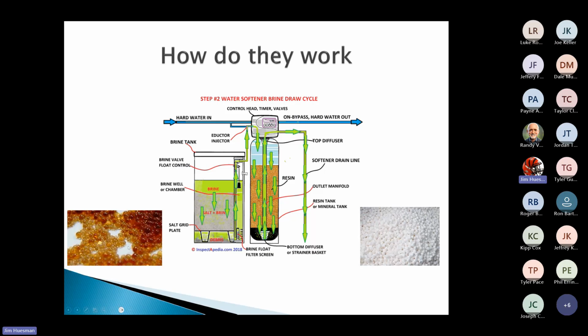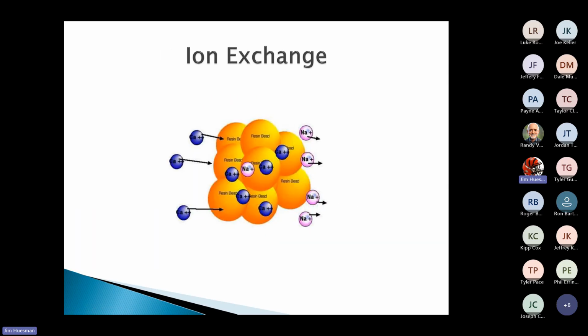But let's talk about what's going on with the media inside this tank. What is this media actually doing? How is it grabbing a hold of it? And the word is called ion exchange. All right, it seems very, very smart, but we're just exchanging one ion for the next. So when the media is set in the tank and it's new or after a regeneration, we have a lot of sodium ions attached to each individual cell of that media. So we have that sodium tied to the media. It's just kind of stuck to the outside.